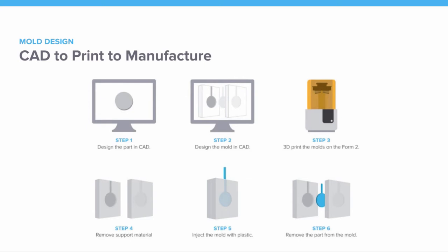You want to be careful when you're using a 3D printed mold. High pressure and high clamping forces can and will probably break the mold, so you want to reduce those. You can, of course, sand and polish the parts if you want. 3D printed molds are especially good for thermosets. If you don't know, there's thermoplastics, which are plastics that have to be melted to be injected, and then there's thermosets, which get mixed, then injected, and then they harden. With thermoplastics, you want to make sure your mold can stand up to the heat and pressure. With thermosets, you just inject them, and you just have to make sure that during the thermosetting process, it doesn't give off too much heat. Otherwise, just use a high-temperature resin.